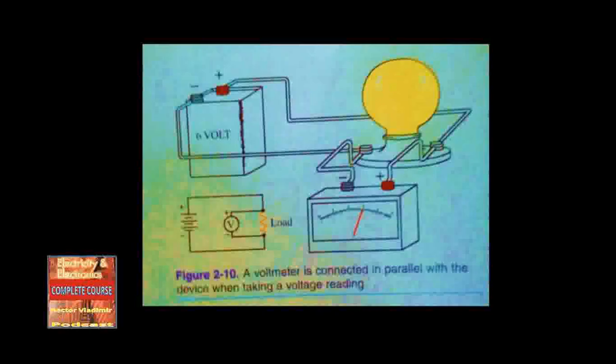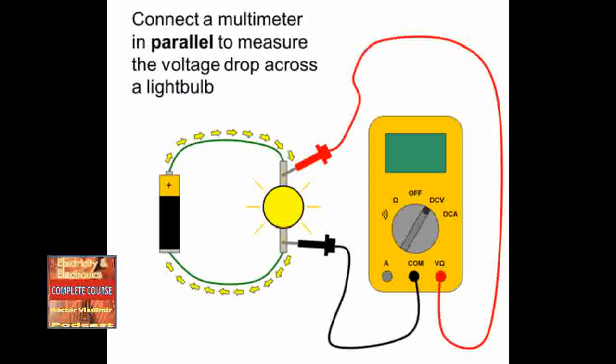2.3 Voltmeter. The same basic meter movement that is used in an ammeter is also used to measure voltage, providing that the impressed voltage across the coil never exceeds 0.1 volts, the same as computed for full-scale deflection. This is important, always as computed for full-scale deflection. To arrange the meter to measure higher voltages, multiplier resistors are placed in series with the ammeter movement coil using a switch. A meter similar to the meter that measured current is used.